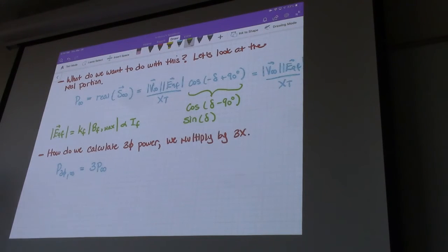So what does this mean, right? Inside of the rotor, you have that single field winding, which is going to be excited with a DC current, right? If we don't supply a DC current on the field winding, there won't be any magnetic field generated, there won't be any flux linkage between the rotor and the stator, then the rotation won't be causing any change in the flux linkage, and we won't get any EMF induced on the terminals, right? So IF is key to making this thing work.